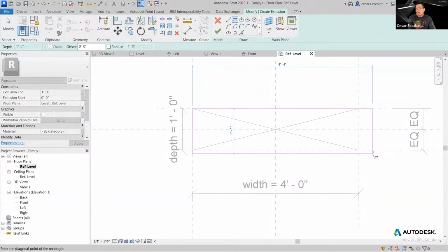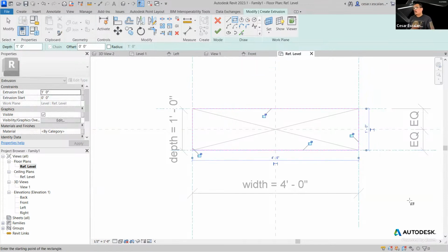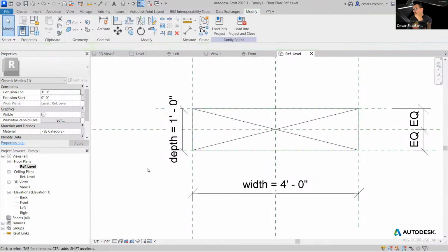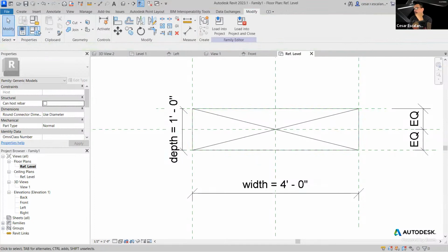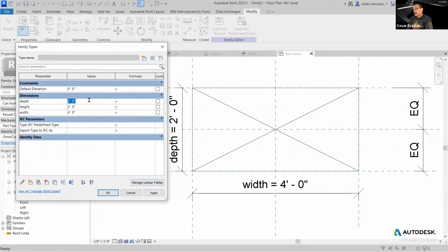And then I'm going to do SI again, right here. There's no need to use those locks. In fact, that is overly constrained because you're creating double locks: the ones that the family does automatically, and the ones the user defined, which is just clicking those locks. I'm going to leave them on lock, and then I click the green checkbox, and let's see if it flexes. Yep.